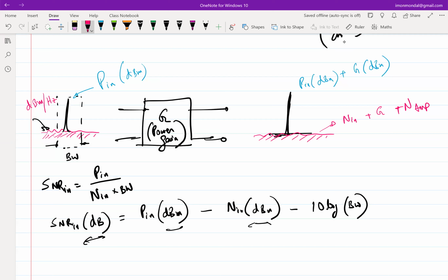So has your signal to noise ratio at the output increased or decreased with respect to the input? It has decreased, right? You have added more noise while processing the signal. The best case is you don't add any noise. You cannot take out noise because it is anyway within the signal band. But if you add noise, how much degradation of the signal to noise ratio you have incurred is obviously a matter of importance, because you are trying to process very low noise and low SNR signals. So that has a technical name, it's called noise factor.